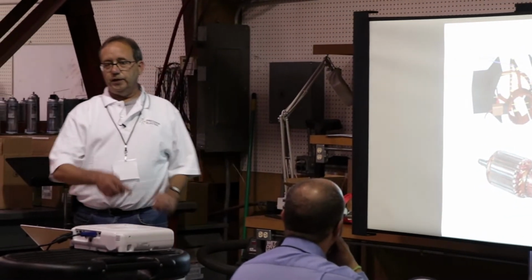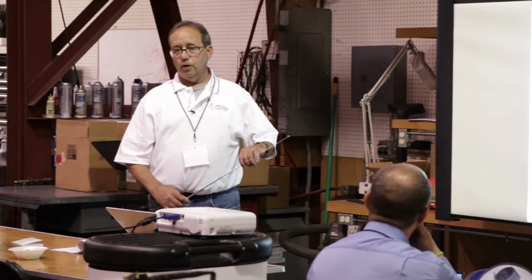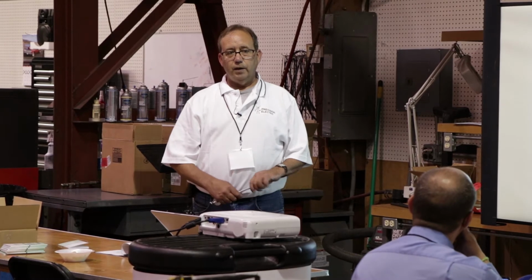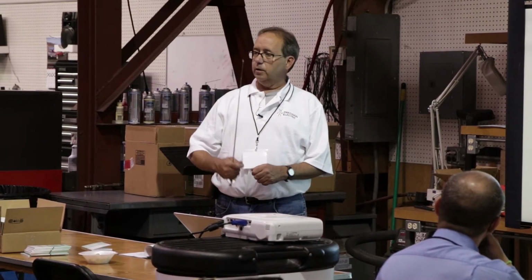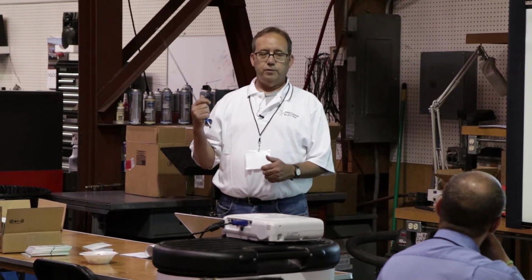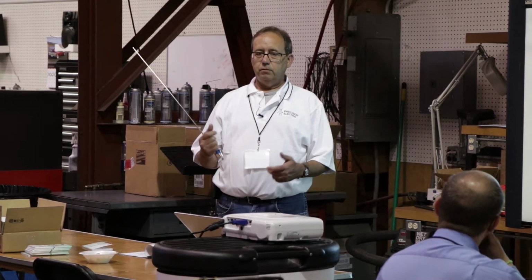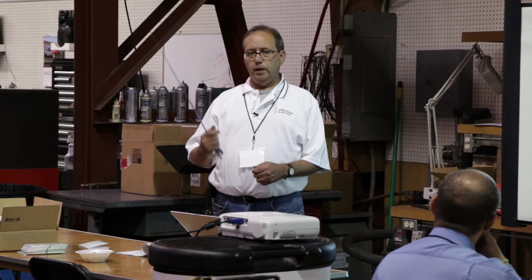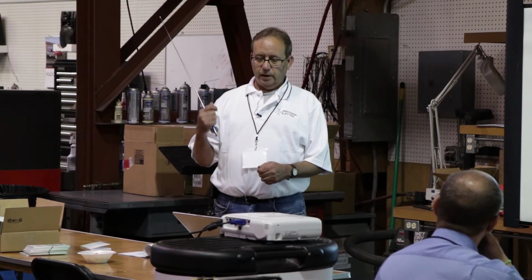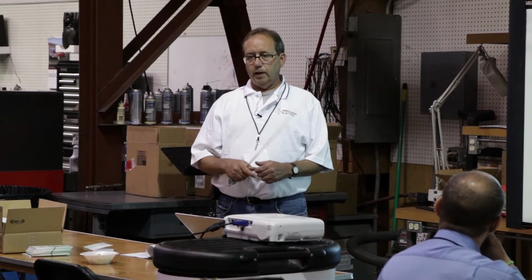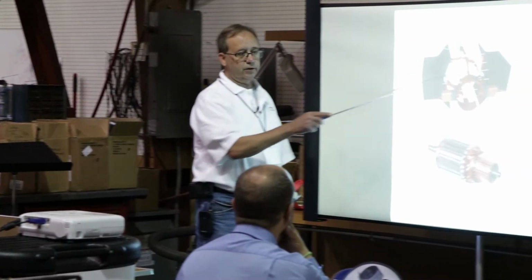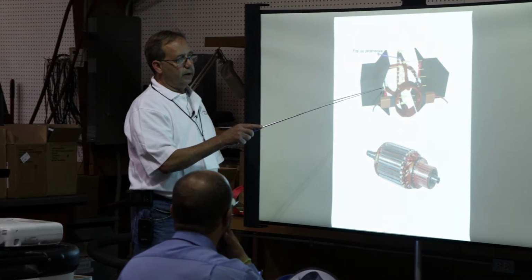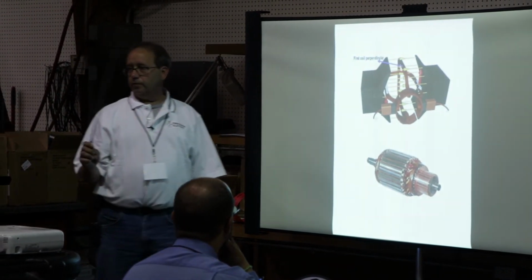On the shunt field, there's a DC power supply built into that little homemade thing. We'll just hit the wire and come off of it. We'll get some current flowing, maybe a couple amps, and we'll watch that amp meter. If this coil isn't exactly perpendicular to this holder, then that needle will move.